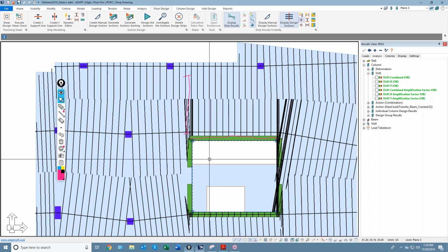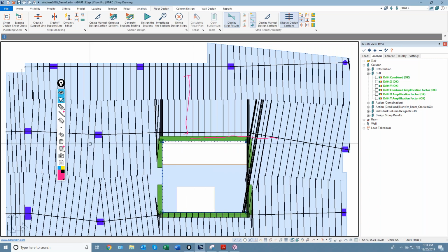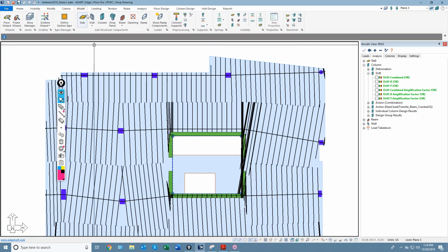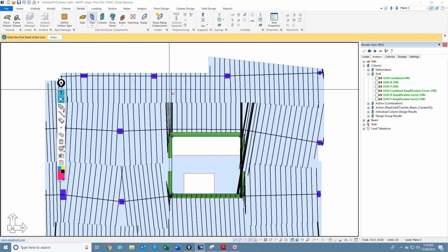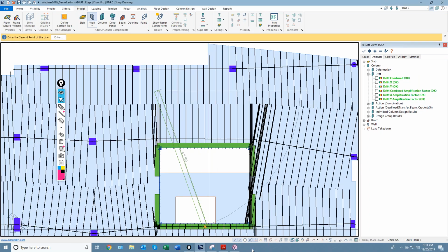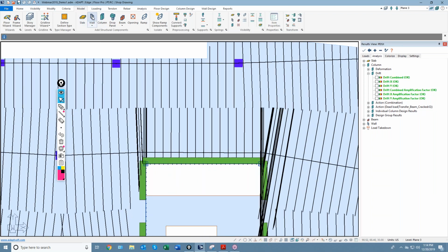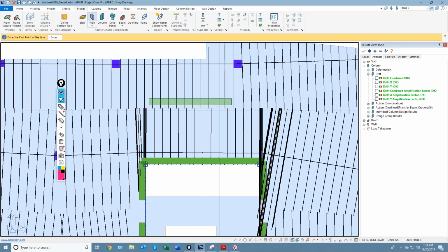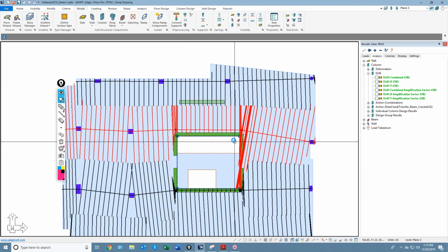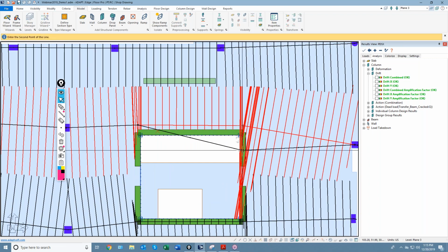This core example is probably not the best example that illustrates this, but let's say you have a wall here. See if I can get that properly input. I'll turn off my snap tools, come back to it. So I'll just add a wall right there. And we want a support line over this frame line, a support line over this line here that we've added. I'll actually move this back down to the wall location.